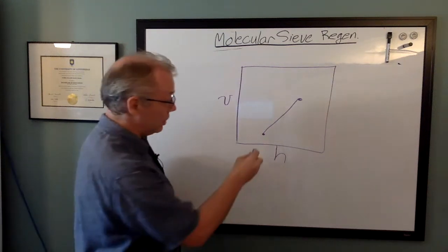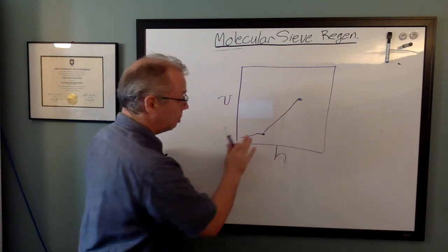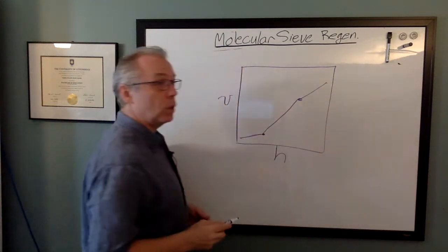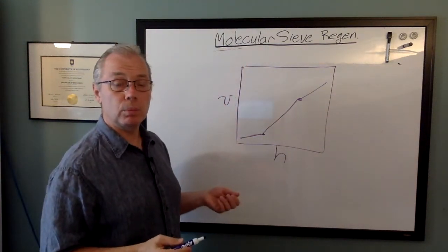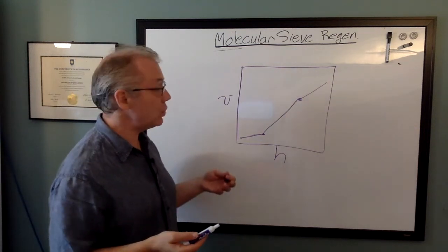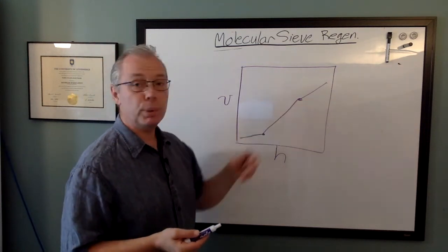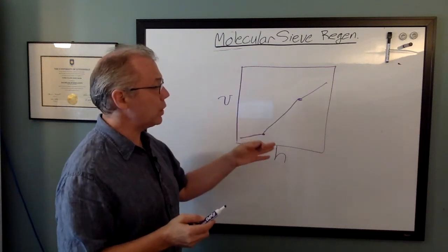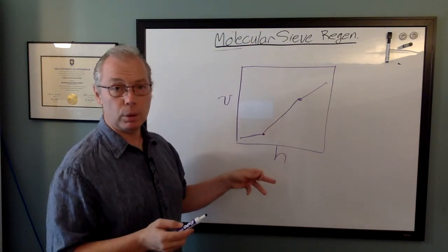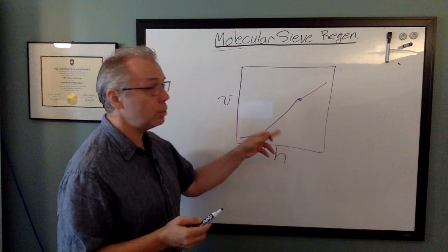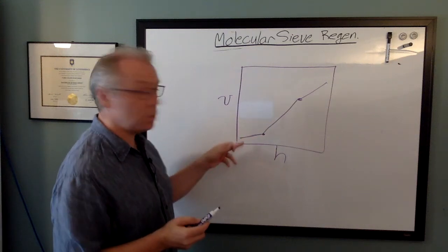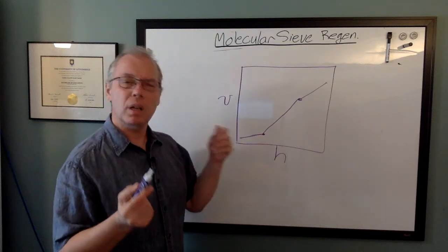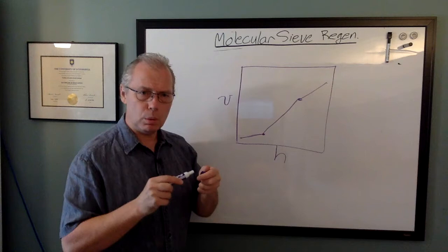Well, we can also extend this out and say that's also true for the subcooled liquid, and it's also true for the superheated vapor. And that's a pretty fair equation of state in the subcooled and the superheated region. Not perfect, but very convenient. And we can write the same sort of equation of state to relate temperature to enthalpy. Temperature is constant in the two-phase region, and temperature decreases in the subcooled region and increases in the superheated region. Okay, so that gives us one of the equations. Now we need a couple more.